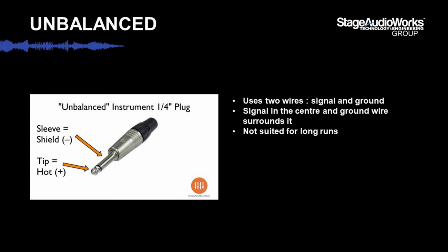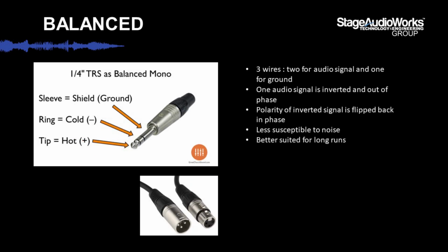So generally speaking, you can use any cable that has this type of connector with just a tip and a sleeve. If we talk about the TRS or XLR, you can see on the jack it has 2 black lines over there. That means it carries a balanced signal, so it has 2 conductors inside the cable and a screen. For carrying a balanced signal, you could use any microphone cable.